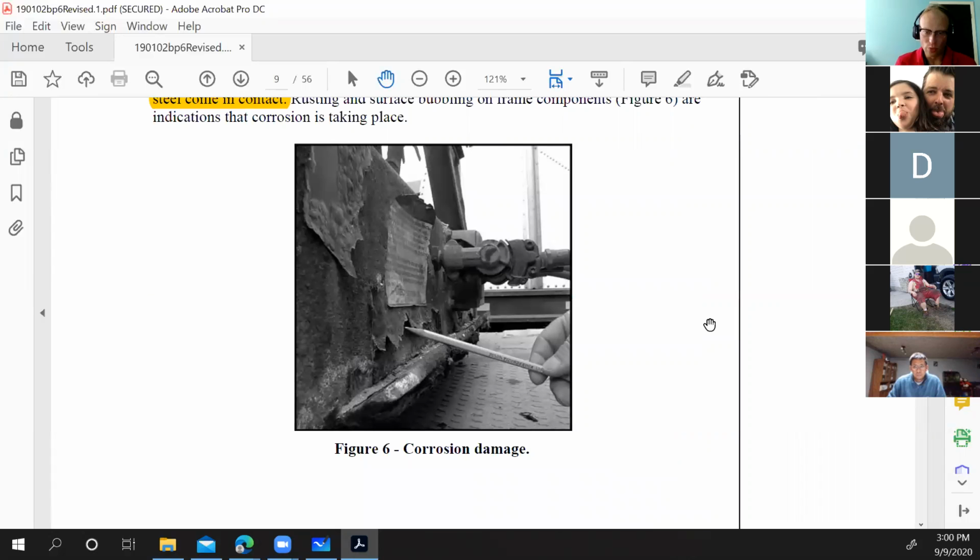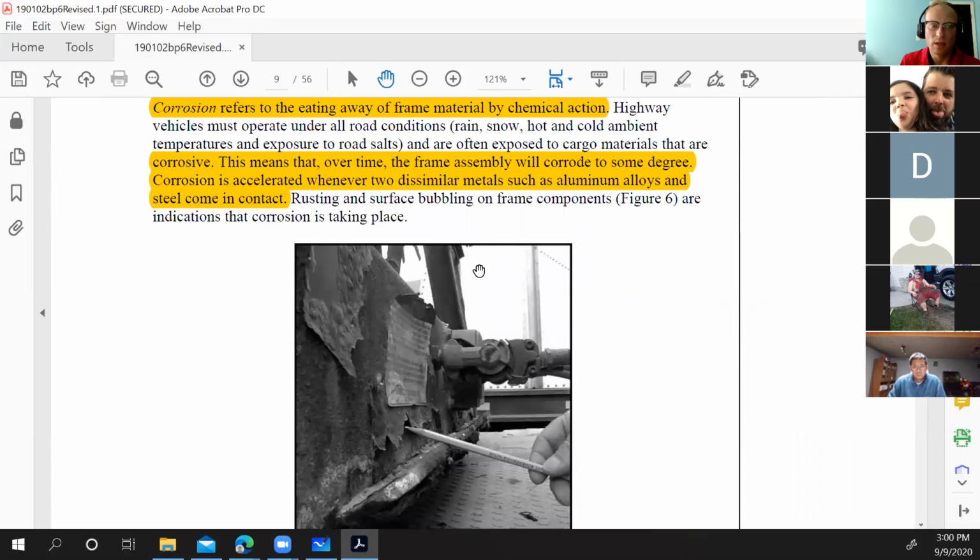There we go, corrosion, everyone's favorite. So this amount of damage. Typically a lot of corrosion problems I had came when two different metals came into contact with each other. So you'd have aluminum with the steel, the biggest problem there, and you get that white oxidation, which is aluminum rust, essentially. It's not termed rust, which is iron oxide, but that's what it is. It's oxidizing aluminum, turning into that white powder.